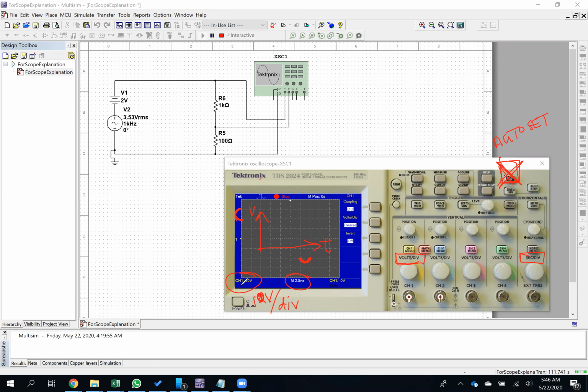So what they don't display on the screen here is that the unit is actually per division. And when they say per division, it's one of these big squares, okay? Not the little tiny ticks, it's a big square. And each of the big squares, with the tiny ticks, is divided into 5. So when you're measuring waveforms, keep that in mind.